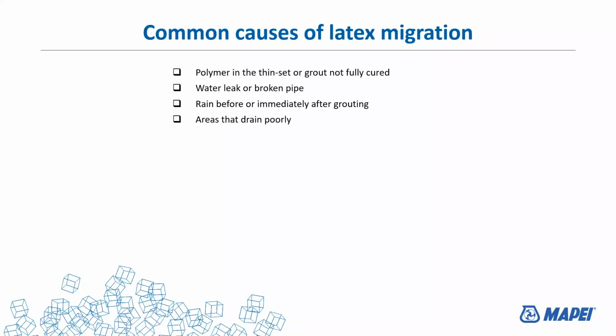That was the worst drainage I've ever seen. The politics of why it's there are completely different, but it is the main cause of that problem. Completely poor drainage. As a matter of fact, I would call it no drainage. There were pools of water sitting on the stone, and they were asking why they had an efflorescence issue.